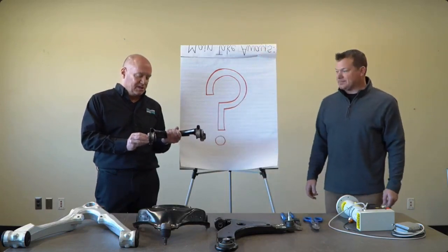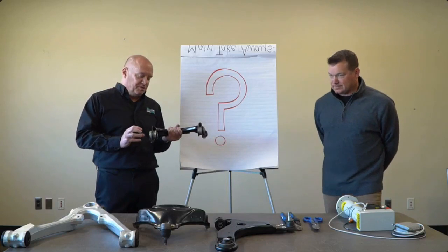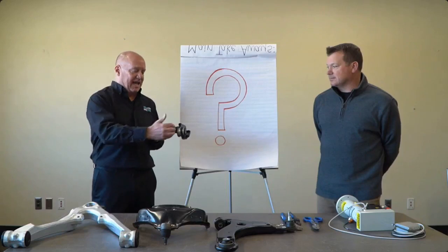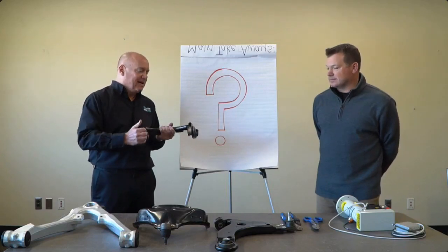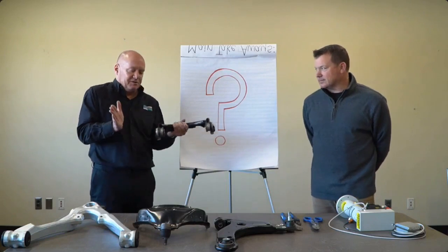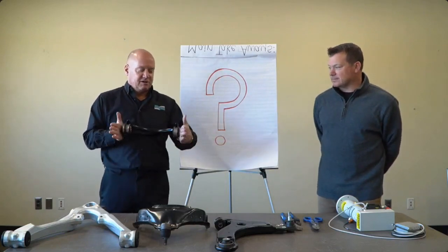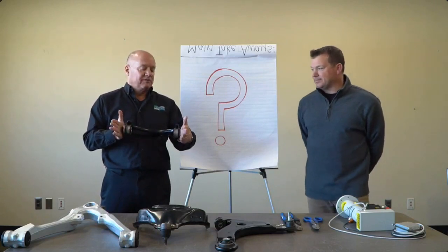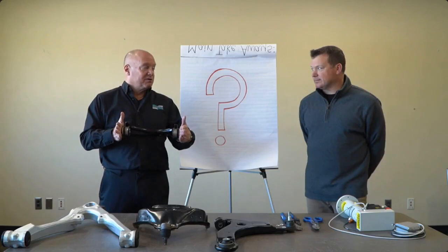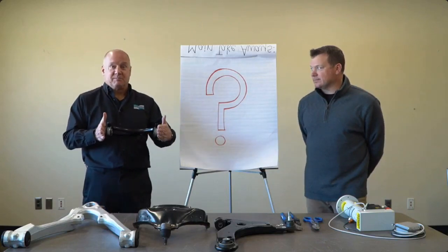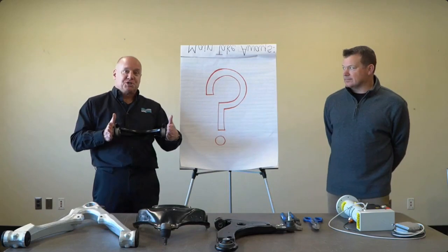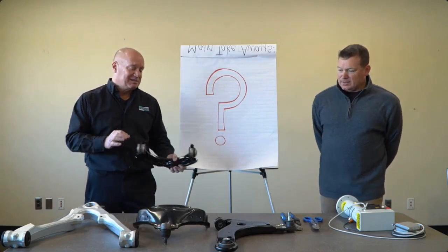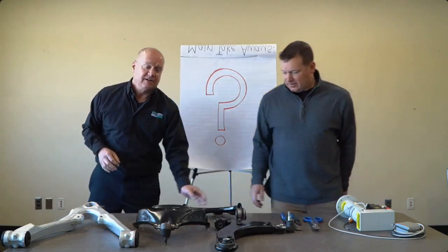If you can imagine pressing these bushings in, you might have thousands of pounds on them. This is not a casting, it's a stamping, and as you're pressing, these ears are closing in, so you get a smaller measurement, and when you take the load off, they may open back up. So we're measuring with the load off, and we have what we call a retract step, where we press, we retract, we measure, and we re-hit. So it's an iterative process. There are a couple of different techniques. Sometimes that's needed, sometimes it's not, but we've done it enough to know how to solve those problems.